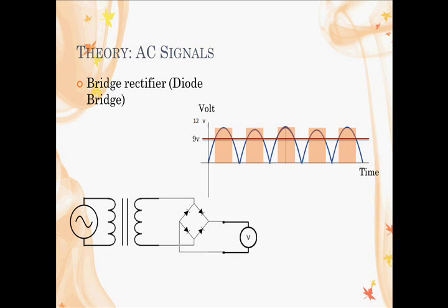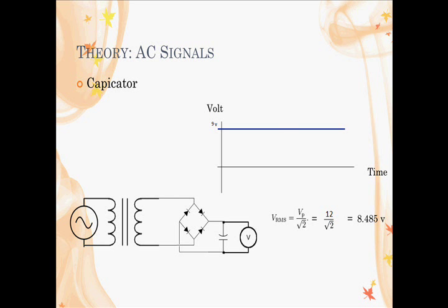So we're going to fix this by adding a capacitor. And what a capacitor does is it opposes a change in voltage. So by adding a capacitor, we can resist the change in voltage, so it's always a constant line. And because we're using an electrolytic capacitor, this is where we get a positive and a negative DC voltage coming out. But still, this isn't an ideal 12 volts, because what a capacitor does is resist a change in voltage, both voltage gain and voltage loss.